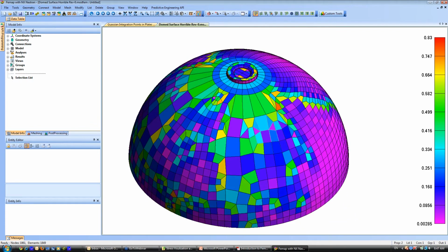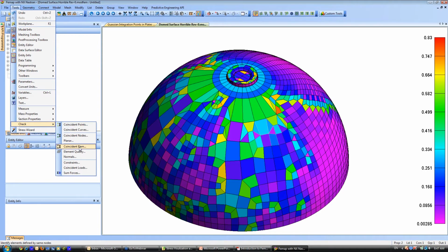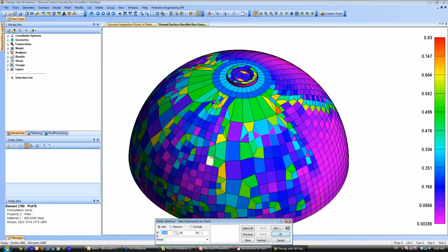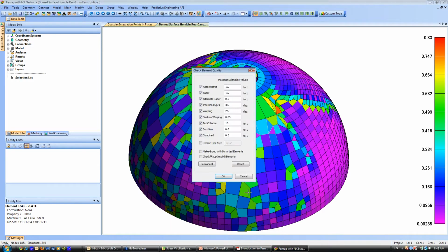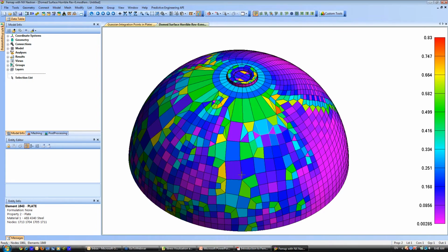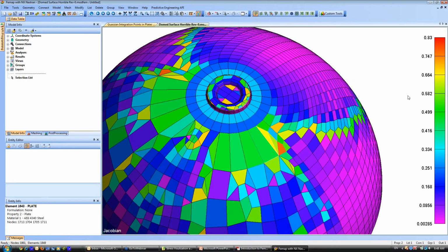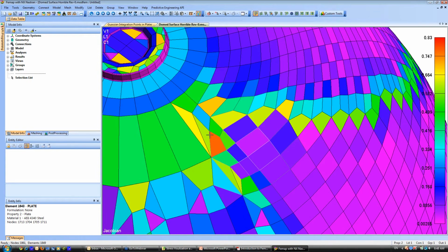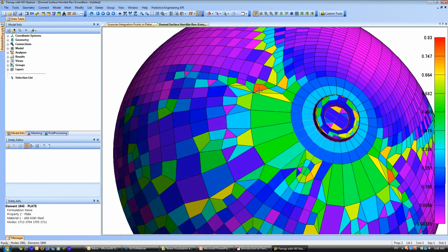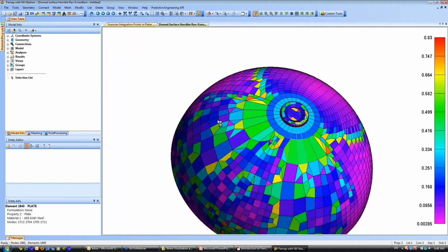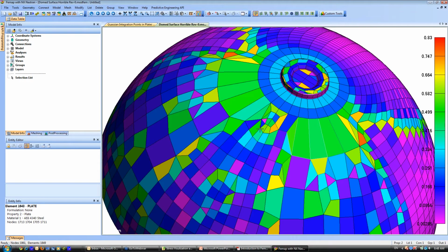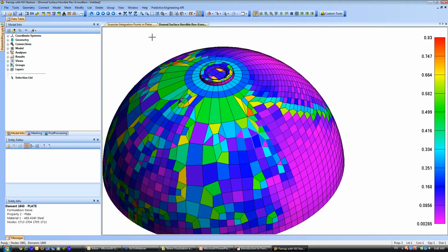And one of the things that you'll see, if you go to Tools, check element quality, and let's just pick a couple elements right there, is that the Femap guys give you some suggested tolerances here. And one of their tolerances for Jacobian is 0.6. And I have no idea where they arrived at that 0.6, and I've asked them that. But actually, 0.6 ain't bad. You can see some of these elements here as they get up near the red, what 0.6 means. And you look at this element right here, and you go, try to break that into a -1, +1 quad, give it up. I mean, you just know some bad things are going to happen with that element. And these other elements being so large and short and triangular, you just got to believe something is not good.